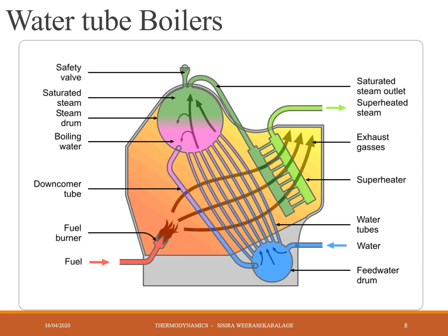So this is the type of water tube boilers. You have two drums here, a lower drum at the bottom and an upper drum, that are connected by a number of tubes. And also, in order to take superheated steam, you don't know what superheated steam is yet, but for the moment say it is not wet. So this is the basic construction for water tube boilers.